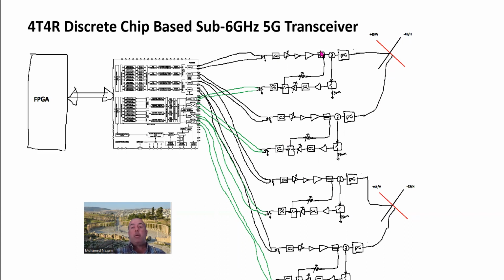So it doesn't stop right here, really. In this case, I showed it ending at a single antenna, but you could also multiplex the signal to go into a panel antenna of, say, 64 of these antennas, okay? So this system can be spatially multiplexing, where you send different information on different polarizations. So you could have this at 1 frequency, this at 1 frequency. So you have 2 beams in here, you have 2 beams, that's 4 beams total. Every beam is carrying different information. That's 4 times the information level that you can transmit and receive. So that's what is called 4T4R.